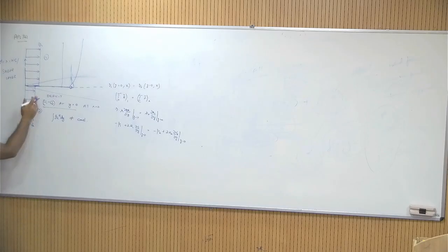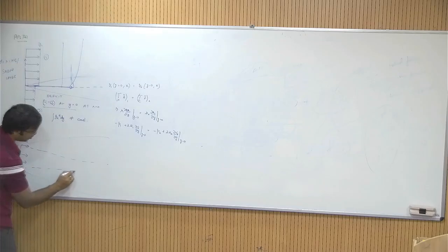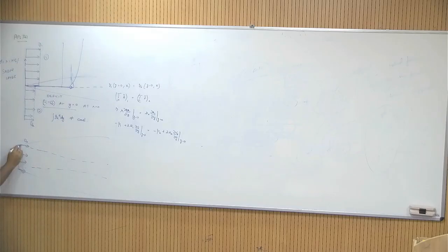And so a jet is a combination of two shear layers, because in jets, let's say you have this and this is constant. As this jet proceeds, here you see a shear layer which is developing, and at the bottom also you see a shear layer that is developing, because at the top the condition is something like 0 velocity and then a u naught, and at the bottom the condition is something like velocity of u naught and then a 0 velocity, and this is what diffuses forward.